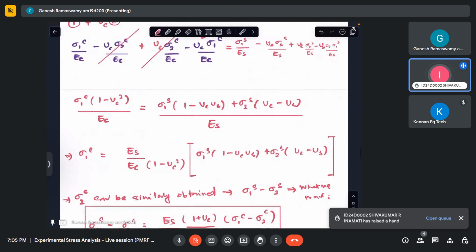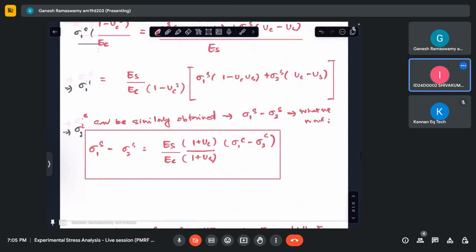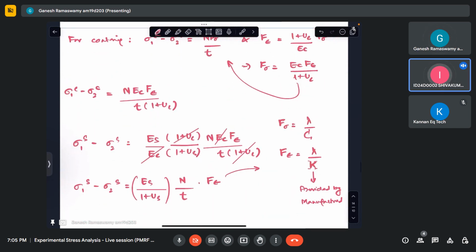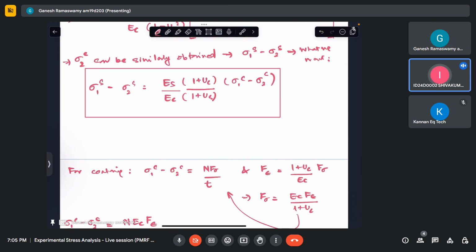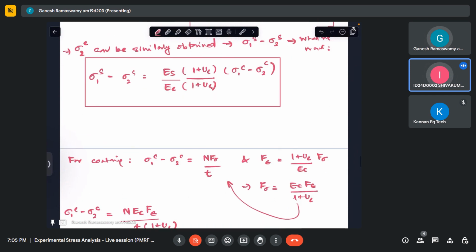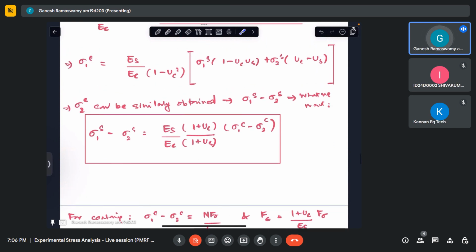That is why it is better to relate it to the length of the light path, then there won't be any confusion. Because for a coating material, let us say the manufacturer has already provided K, then there is no reason to do all this. But in case that is not provided, then we may as well pull it using a transmission photoelastic experiment and evaluate it, and using this relation which we had somewhere, we can back calculate. That is the basic technique.